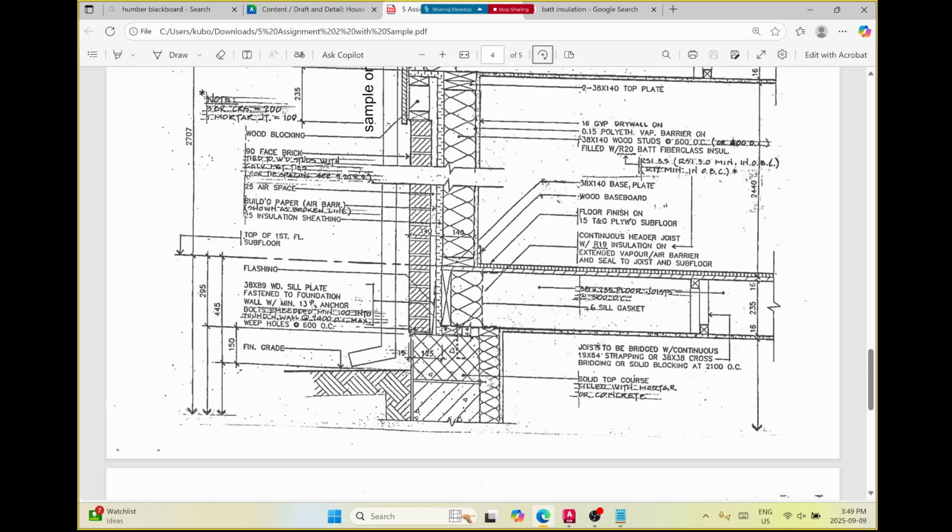And here the dashed line changes. It's now a net, kind of a grid on a diagonal. The reason for that is because this block signals solid top course filled with mortar or concrete. Concrete blocks, you may have noticed, have these holes in them, these two voids. I can Google it for you. This signifies that they are filling those voids with concrete, with mortar. So these ones are hollow, and these ones get filled with mortar, because next class I'll explain it.